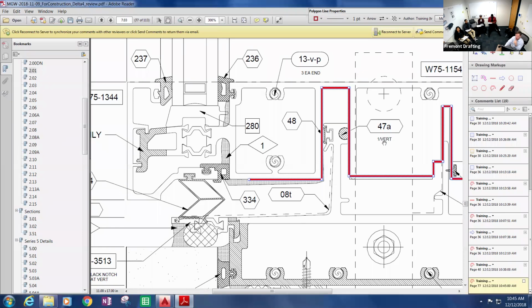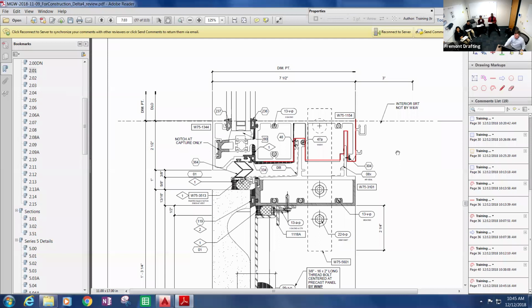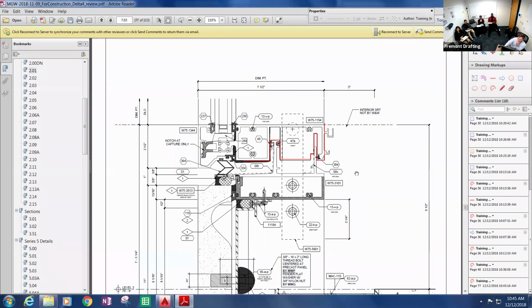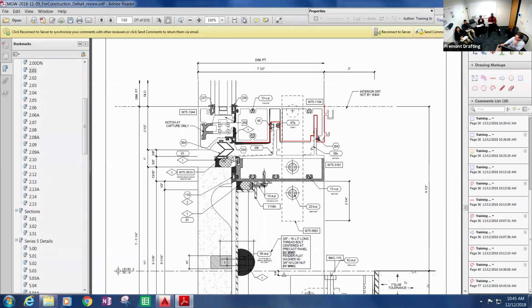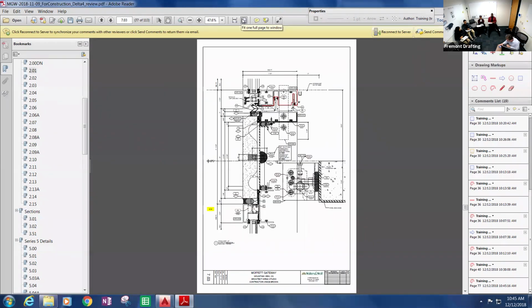And so then when this is in a dead load condition, maybe it's at a sill next to a door, or maybe it's got a soffit above, what they do is they just modify that notch so that it sits hard right there on the chicken head. So now the dead load, just like the other one, is transferred into that chicken head. Is that cool? Good?